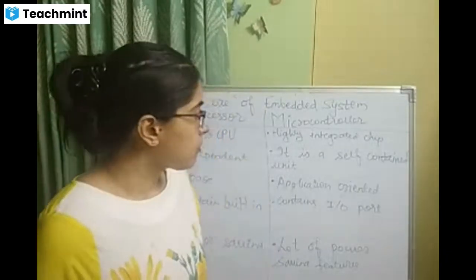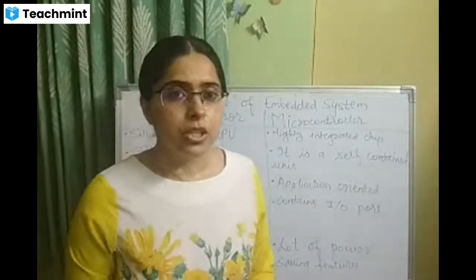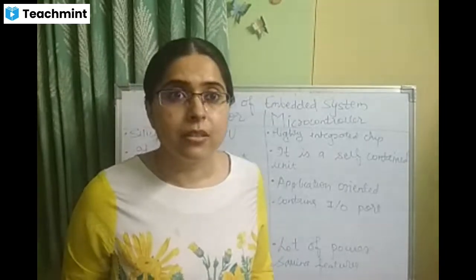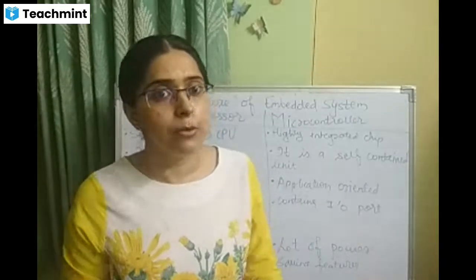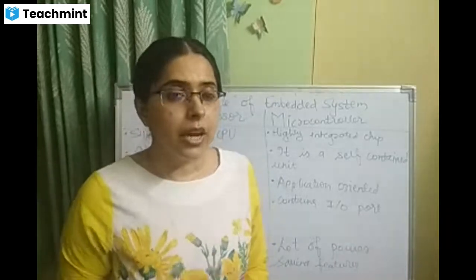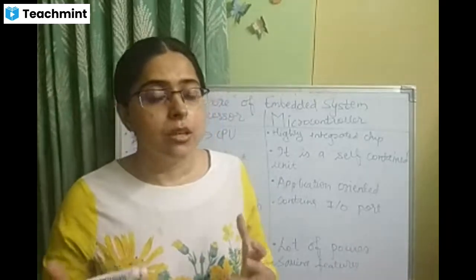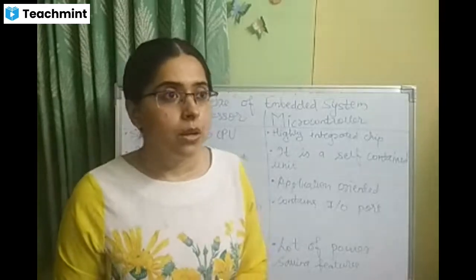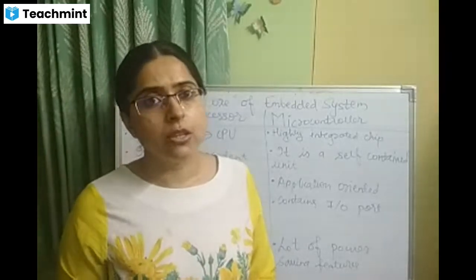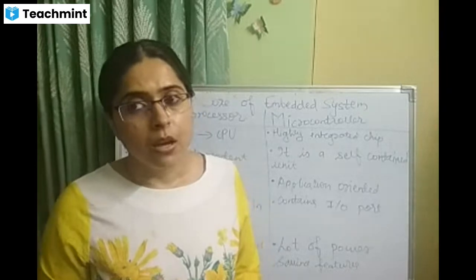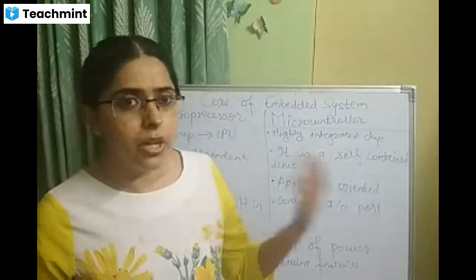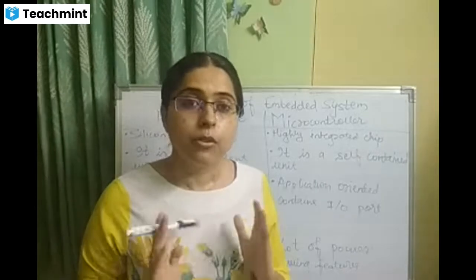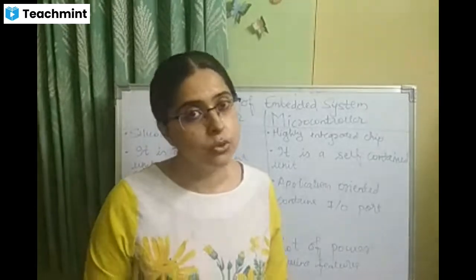Okay. Now next is the digital signal processor. What is a digital signal processor? As its name indicates, it is used for processing of signals. It can be an 8, 32, or 16-bit general or special purpose processor. Digital signal processors are 2 to 3 times faster than a conventional microcontroller or processor. Why? Because of the architectural difference between the two.